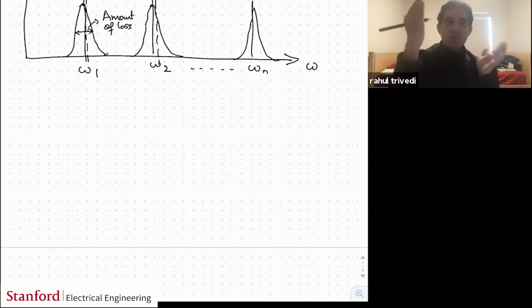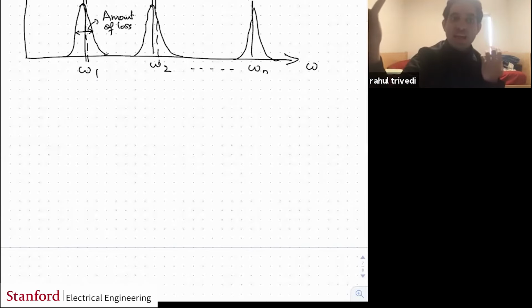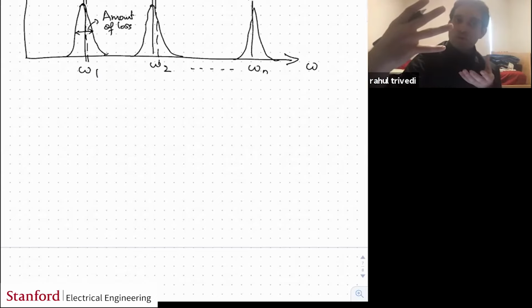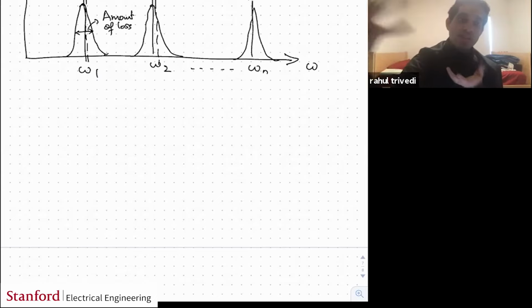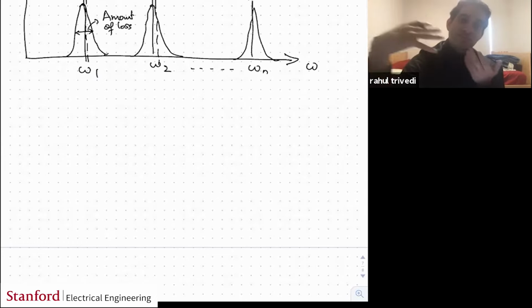you're typically only looking at frequencies that are close to the frequencies that your source is going to be exciting, right? So in practice, you're never really exciting with arbitrarily high or arbitrarily low frequencies. There is a frequency window that's of interest, and then you can focus your analysis on calculating frequencies within that frequency window, right? Also in practice, if you look at practical losses like coming from absorption or radiation, those losses also select some resonant modes to be very, very lossy. So even though in a lossless system you will have infinitely many resonant modes, most of those resonance modes that would exist in a lossless system would become incredibly lossy in the presence of any practical losses. So you wouldn't actually see a resonance there.